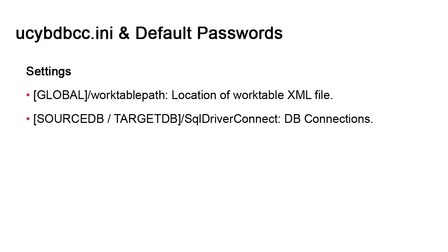The source DB and target DB sections contain standard SQL Server connect settings that are common to all DB utilities. These contain the ODBC database connection settings. By default, the two are the same, and so your client copy will happen on the same system. But you can use the ODBC connection string from another system. In doing so, you'll copy the client to that particular system. They don't even have to be the same database package.